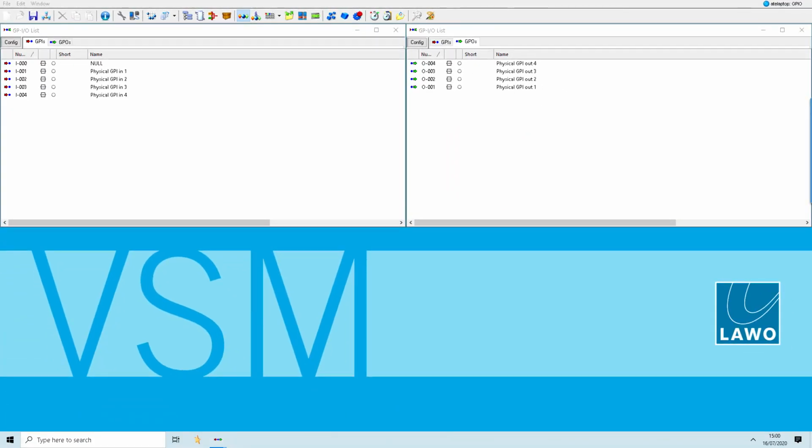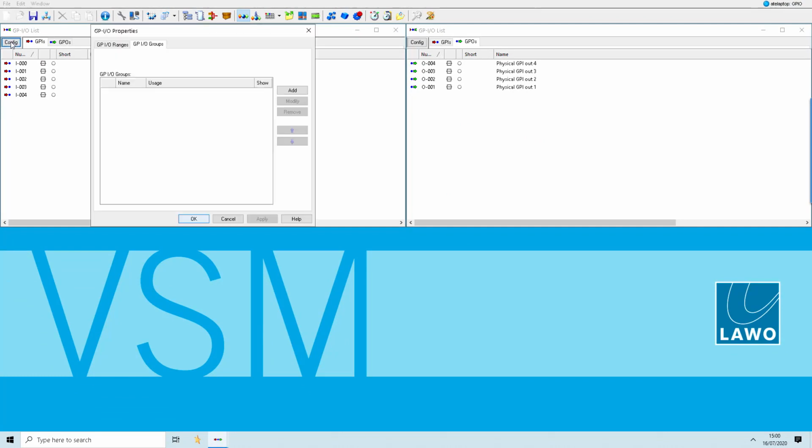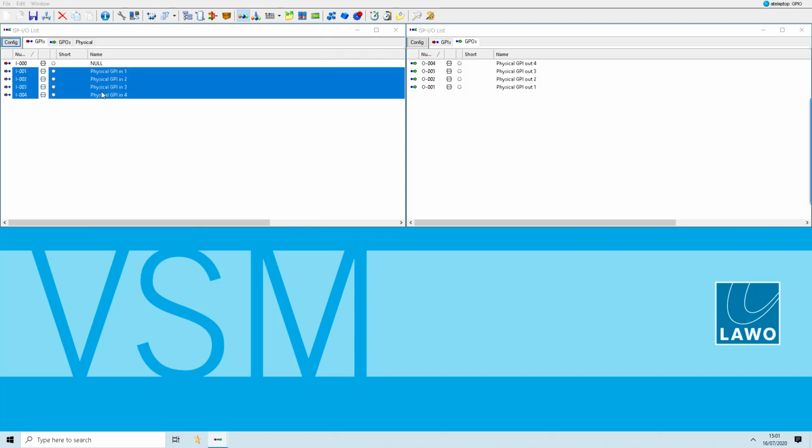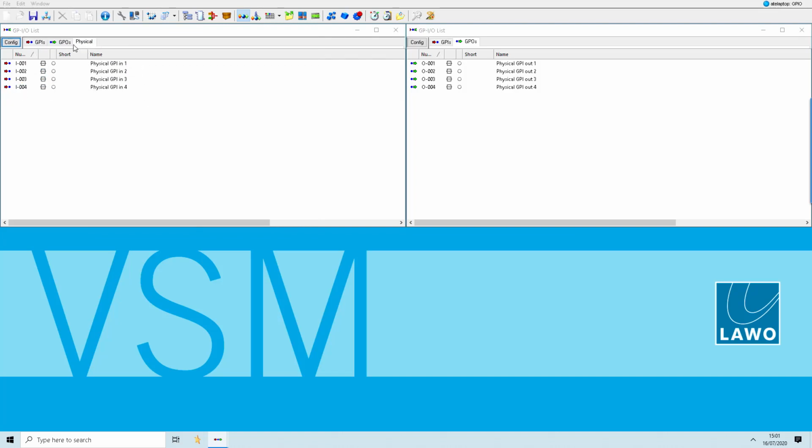If you want to keep things tidy, it's always a nice idea to go into the config and create additional columns. I will create this one called physical. And now I have a new tab called physical. There's nothing in there right now. So I'm able to drag my GPIs by selecting them into physical and also my GPIOs into physical. And now you can see that in the physical tab I can see all of my ins and outs. I can order them by number or by their names.